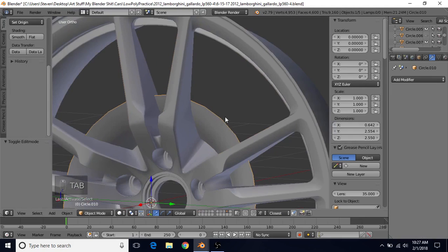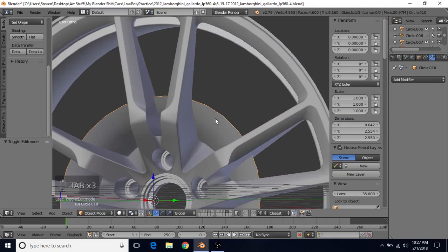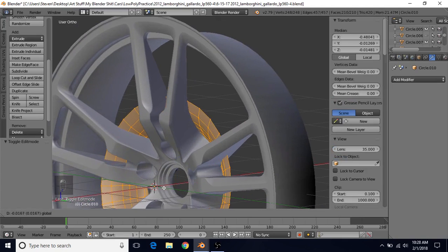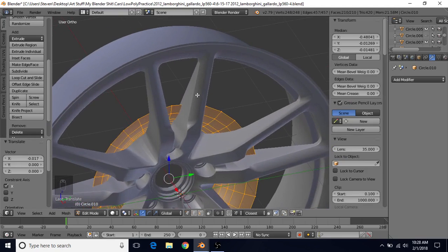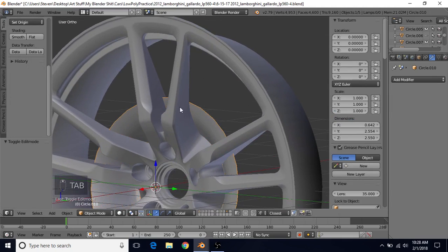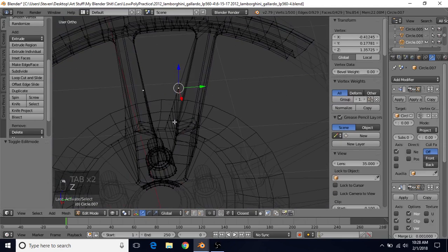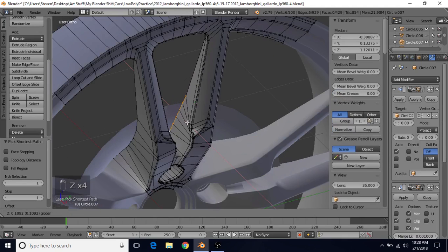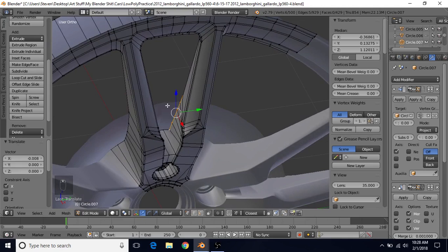So now what we want to do is select on this bowl shape that we have. Just go to object mode, select this thing, press tab, and just bring it back some so that it's further on the x-axis than the rest of these vertices. These inner ones on the rim will have to adjust, and we're also going to adjust this shape as we go along. Then press tab again, select the rim, press tab. So we're going to move these vertices forward some. So we're going to select this one, hold Control, select this one, Z for wireframe, and then bring these back some, just so that they are further along than this piece.